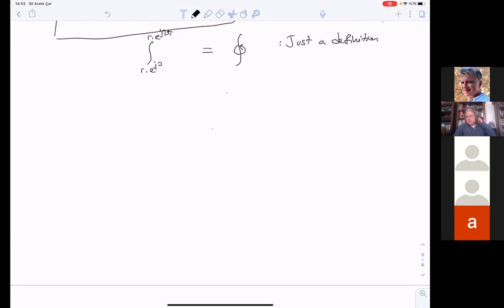So how will you find the inverse Z transforms? The classical way of finding the inverse Z transform is to put it into first order forms if you can, like the Laplace transform. And then from the first order systems, together with the region of convergences, you will take a look at the table, what it corresponds to. And from the table, you say that this part corresponds to this signal and this part corresponds to that signal, and you combine them. That's how you will find the inverse Z transform.